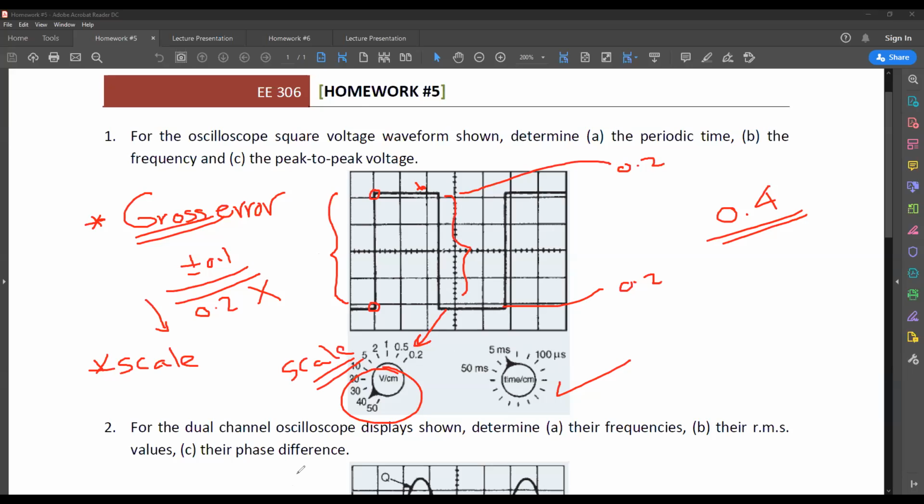This was a very common mistake. Student: Doctor, times 40 times 10 to the minus 2? No, where can you see the 10 to the minus 2? This is centimeter here, and this is centimeter here. So just leave it as it is, 40. This is what you have on the scope. Each one of these marks is 0.2 centimeter. So this was a very big mistake.